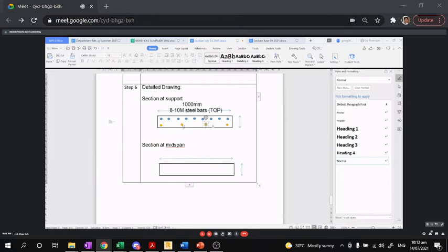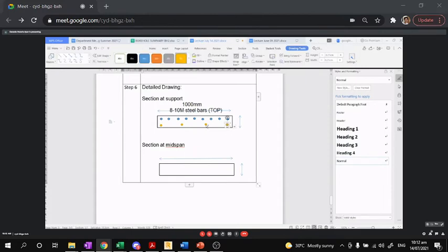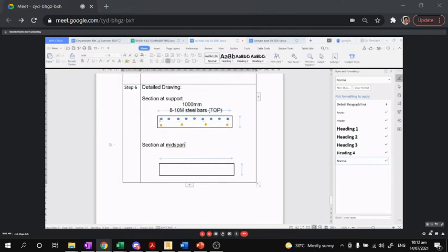So I will group it. Okay. I must also not forget to place the concrete cover, 150 here, but if I move it here, 125. Total depth. So, I will place 3 10 mm steel bars at the bottom.